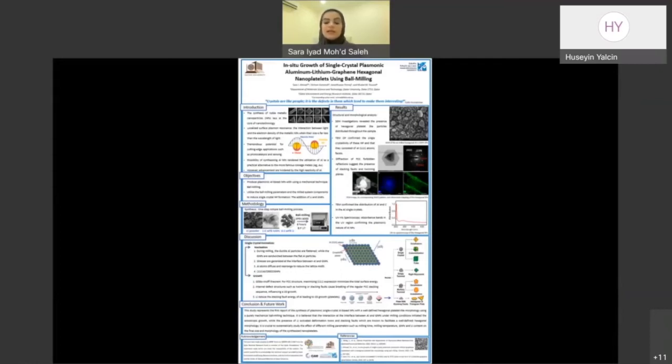In general, single crystal formation happens in two steps, nucleation and growth. The single crystal formation first requires a nucleus, a template, or a substrate on which the crystal growth is initiated and directed. Now, during milling, the aluminum particles or atoms are forced into contact with the graphene nanoplates. However, the initial incompatibility between HCP graphene and FCC aluminum generates lots of stress at the interface.